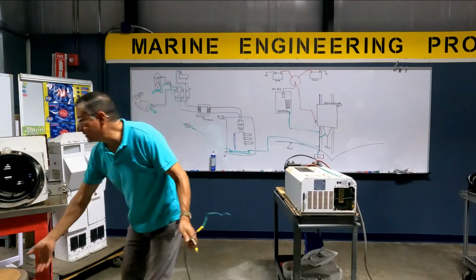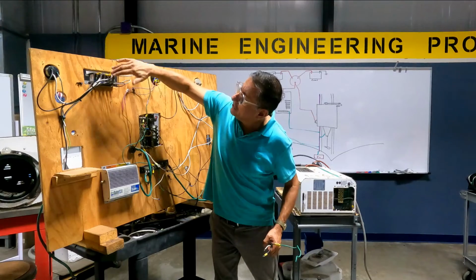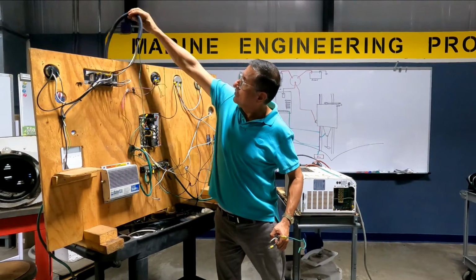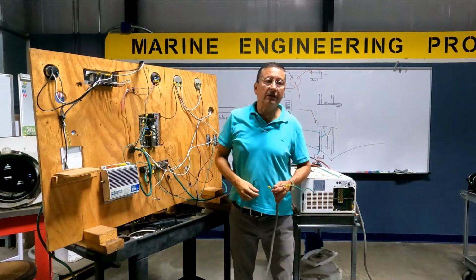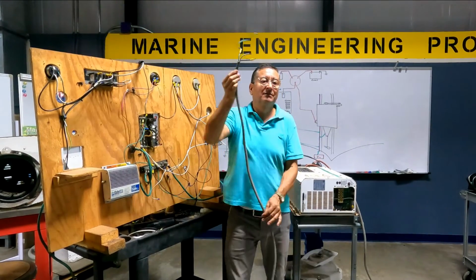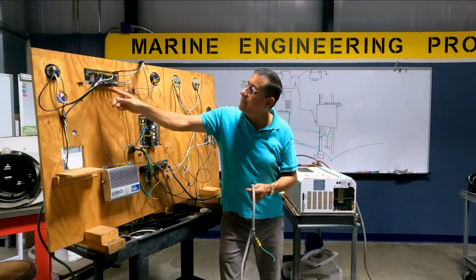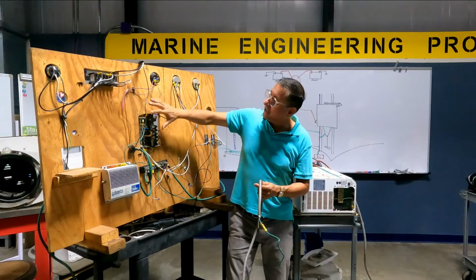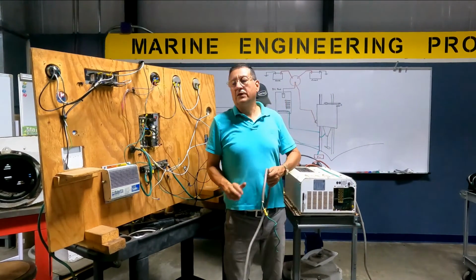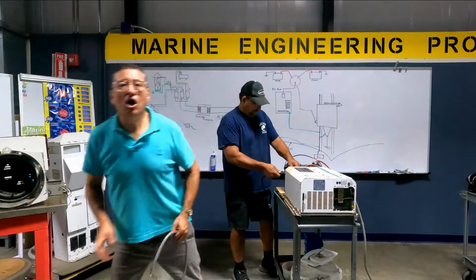How? Like this. I have one breaker for inverter, another for generator, and another for shore power. Shore power, this one for generator, and the other for inverter. This is the cable that enters here in one of the breakers. That's clear, my friends? And in the bottom, I connect the outputs ready to feed the panel. Good? Okay.